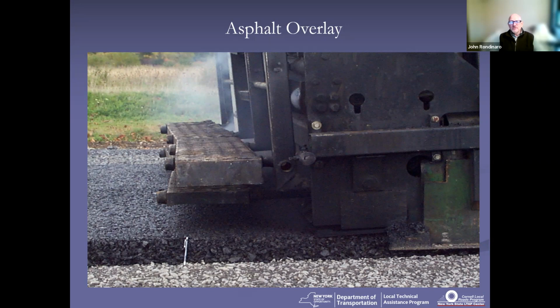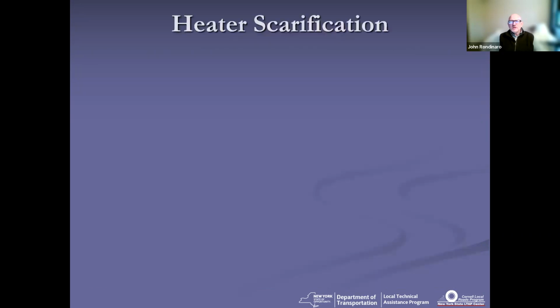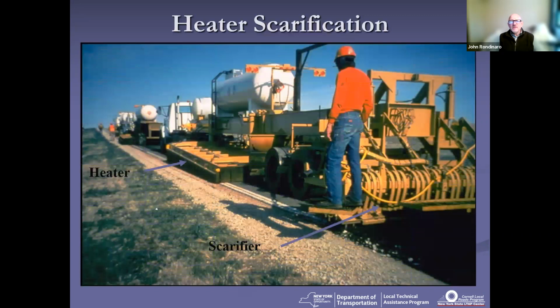One thing you always got to take into account when you're thinking about your overlays, you've got to be considering your curb reveals. You've got to be thinking about your guide rail heights or any other appurtenances. You've got to be thinking about your underground utilities and drainage structures, and you've got to be thinking about any of your overpass clearances.